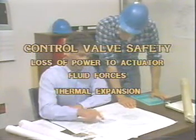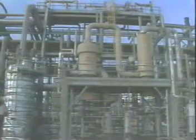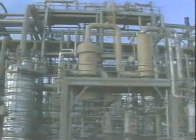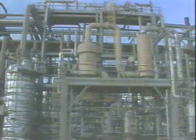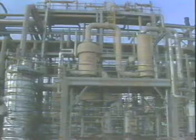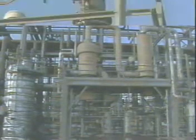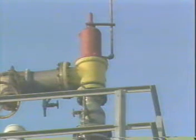Thermal expansion of liquid in a control valve can also create a safety hazard. There are applications where liquid can be blocked in by a control valve and then heated by an external energy source. This can result in a pressure buildup that could easily cause a valve or piping failure. Pressure relief devices should be used to protect against this type of potential problem.